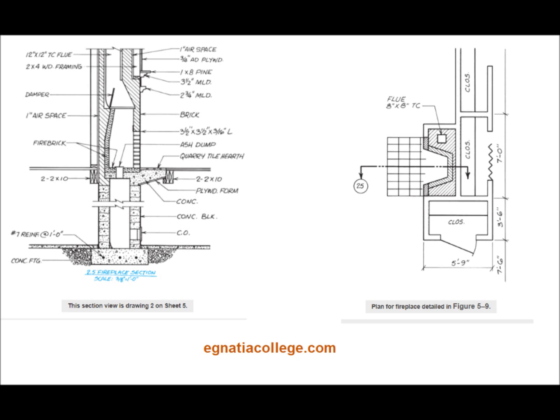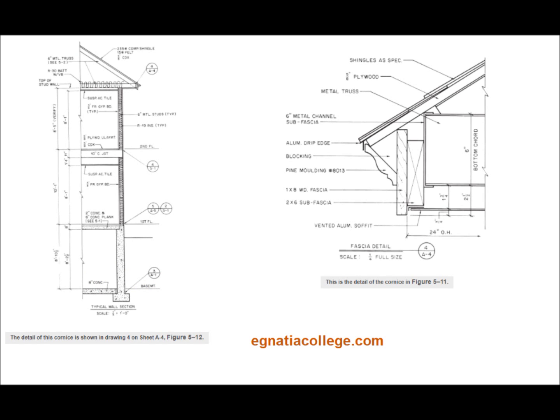The simplest numbering system for drawings consists of numbering the drawing sheets and naming each of the views. For example, Sheet 1 might include a site plan and foundation plan. Sheet 2, floor plans. And Sheet 3, elevations. Because most of the drawings for a single-family home are architectural, and the drawing set is fairly small, letters indicating the type of drawing may not be included. Instead, the views are numbered, and a second number shows on which sheet it appears.